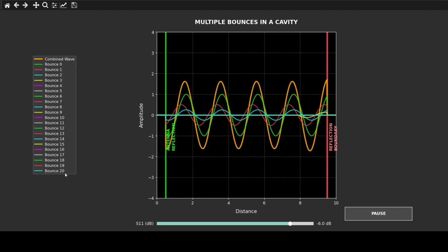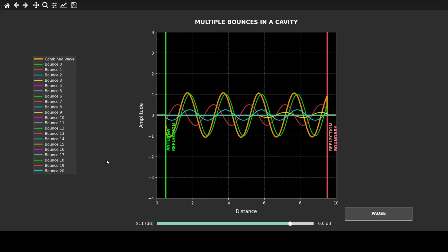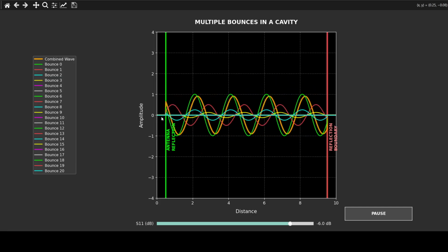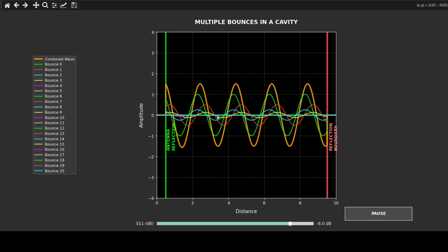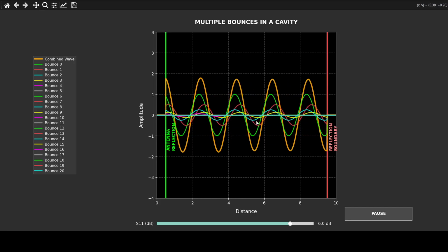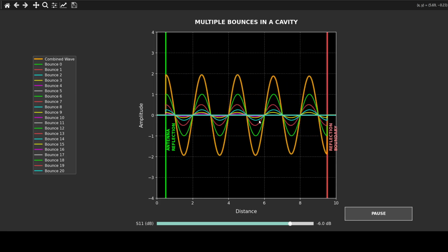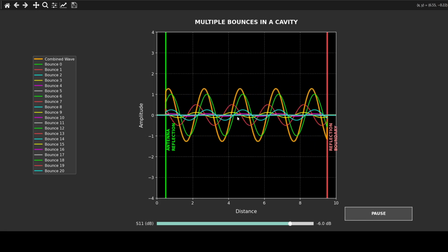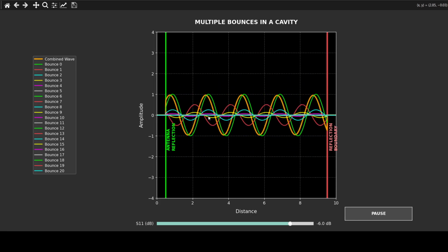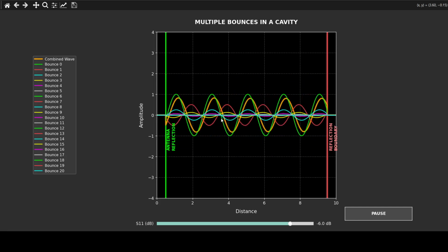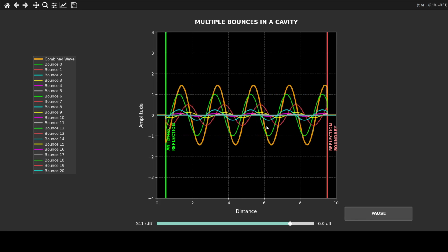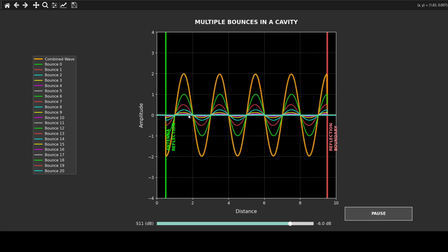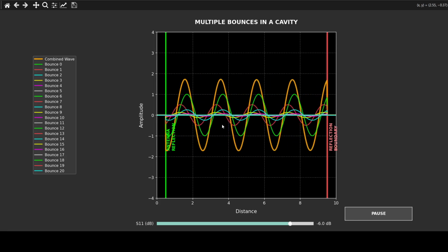So in this simulation, I've just considered 20 bounces here. One thing is that I consider this transmission line to be a short transmission line, right? Meaning that you can see as the wave is traveling, its amplitude is not being attenuated, which is usually not the case. When the transmission line is longer, the reflection as it's traveling back to the source gets more attenuated. But for the sake of demonstrating this idea of impedance matching, say the reflected waves do not get attenuated, right?